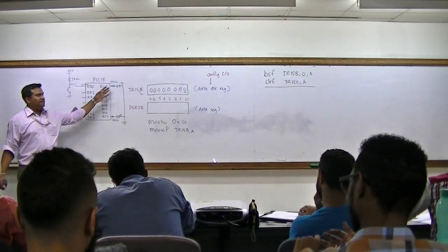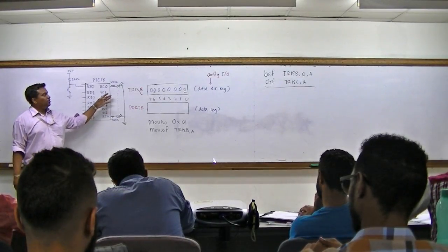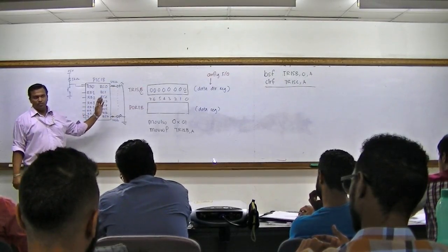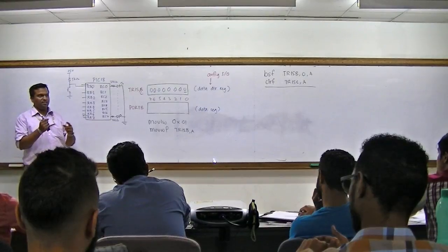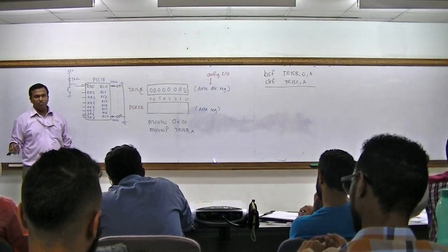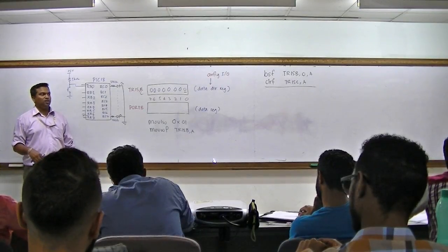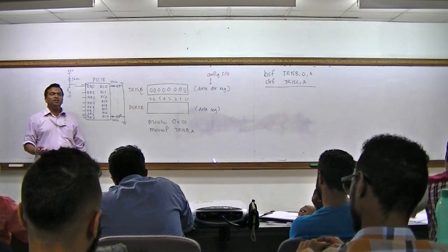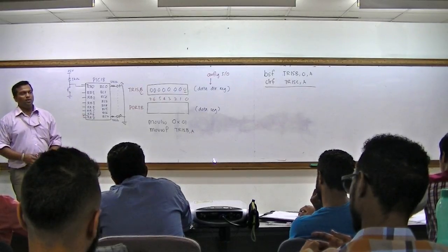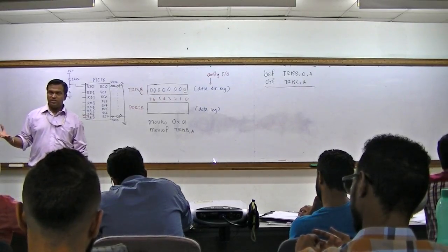For example, here the LED, right? You may want to initialize it so that it is off initially. If you don't do it, sometimes you can see the LED tend to blink here and there. You want to forcefully initialize it to 0. Now that depends on the question. Sometimes the question requires you to initialize it to 1, which means they want the LEDs to be on first.